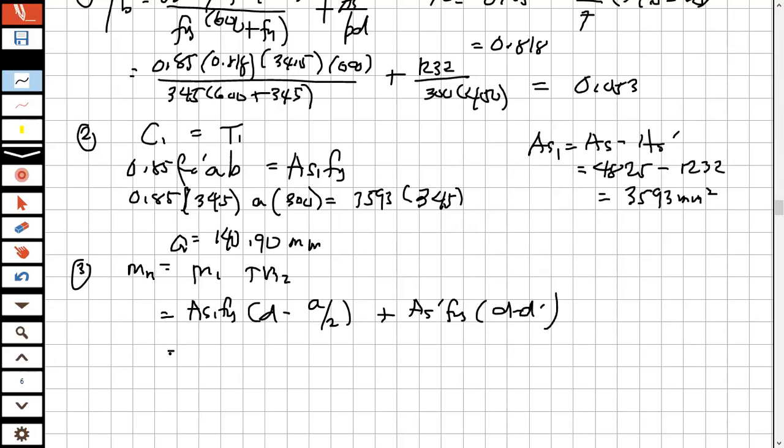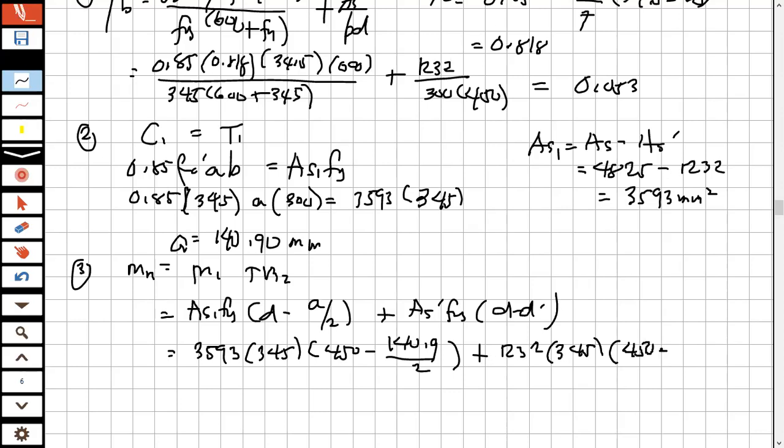Okay? So you have As1, 3593, fy is 345, d is 450 minus a na 140.9 over 2 plus As' na 1232, fy is 345. d is 450 minus d' na 65.